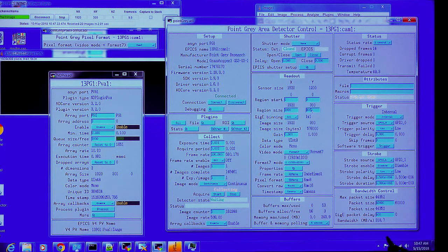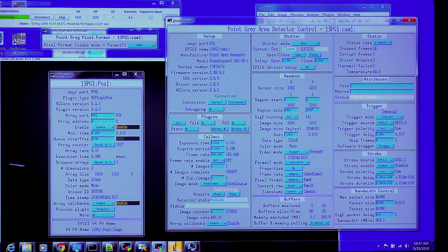And that's true. This is a CMOS camera, but that's often true of CCD cameras as well. If you only read out some of the rows, it's faster. But if you read out fewer columns, it doesn't speed it up. So if we go back to 1200 here.